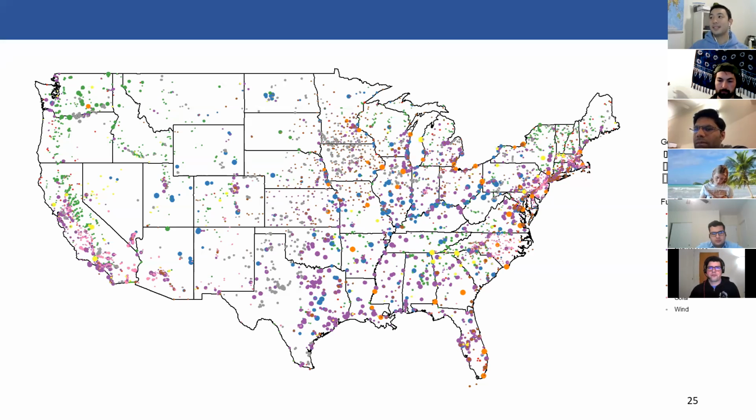And so all these power plants will put in bids, right? And so you build what's known as a dispatch curve, which is you order the power plants one by one based on how much they're bidding from lowest cost to highest cost. And you basically turn all the power plants on up till the last amount that you need. And whatever bid that last person had is what everyone gets paid.